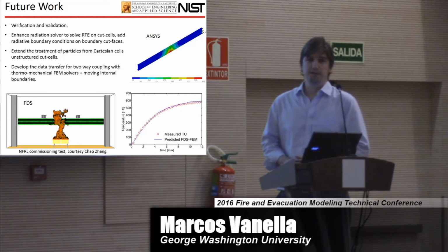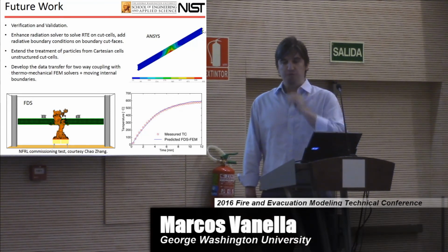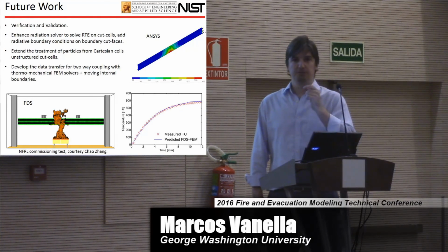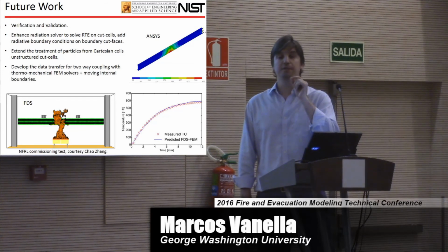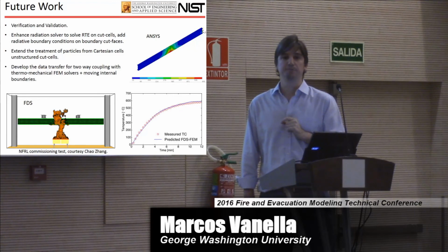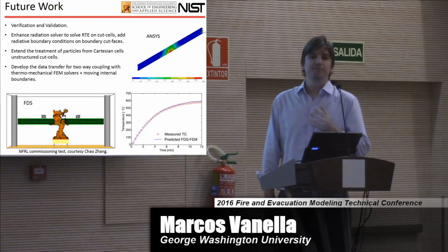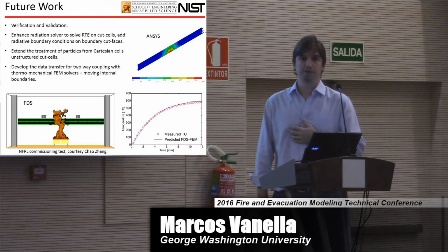At this point, what we do with LES is mainly we do interpolation of the turbulent viscosities using Van Driest damping into the underlying Cartesian cells, and that's what's being used in the evolution of momentum. As in every LES calculation, we don't resolve the boundary layer. We cannot afford it.